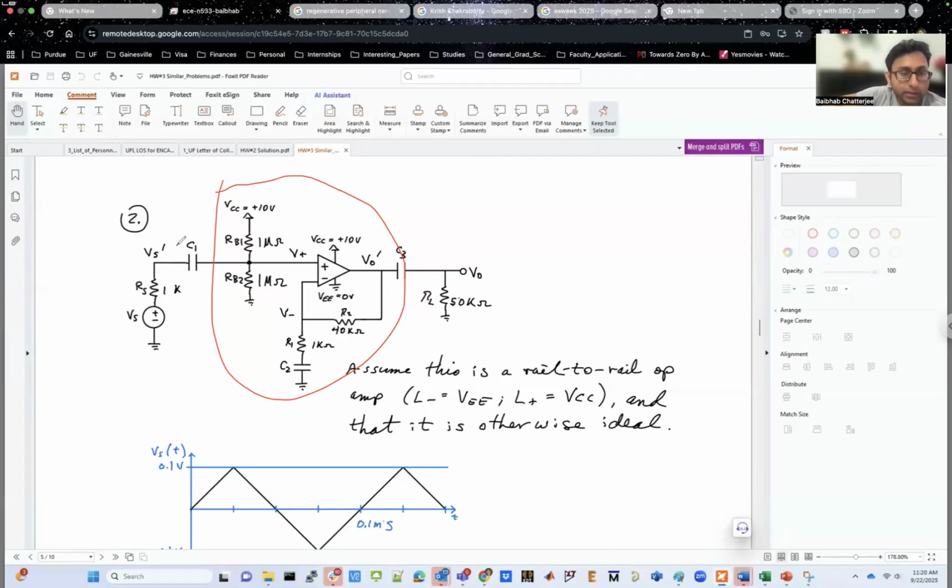And that's the reason why you put these DC blocking capacitors at the input side and output side. They are sometimes called DC blocking capacitors. Sometimes they are called coupling capacitors. Why coupling capacitor? Because they couple the AC but block the DC. So you can call them the DC blocking caps. You can also call them coupling caps.